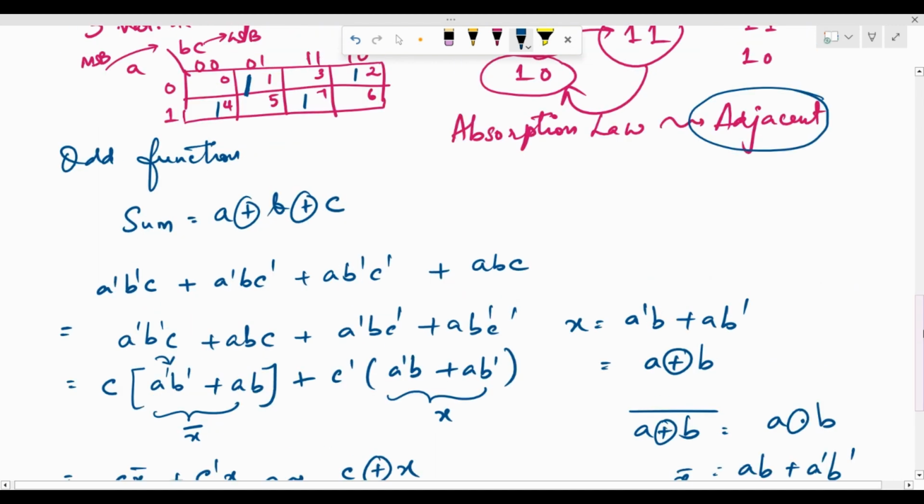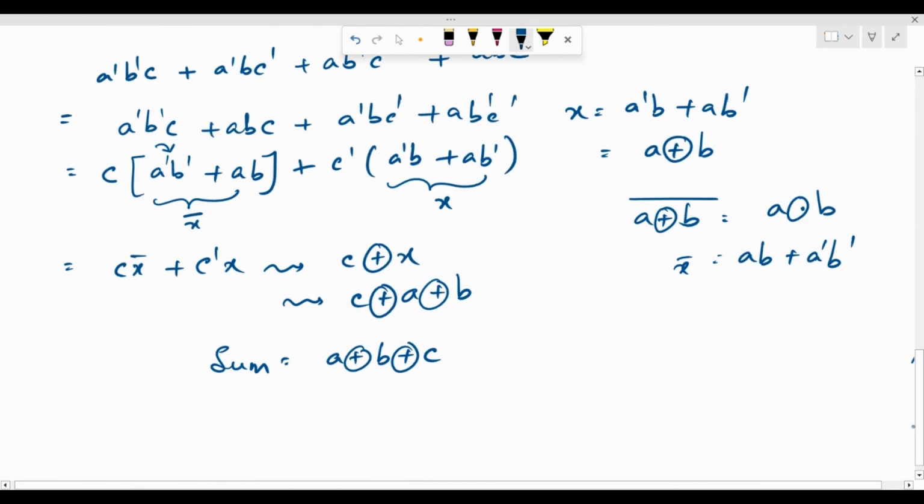So even if I have a four variable K map and I have this brick wall arrangement, say that inputs are A, B, C, and D, then the expression for that particular function of the K map is going to be the XOR of A, B, C, and D, right? So this is the expression for the sum of a full adder.